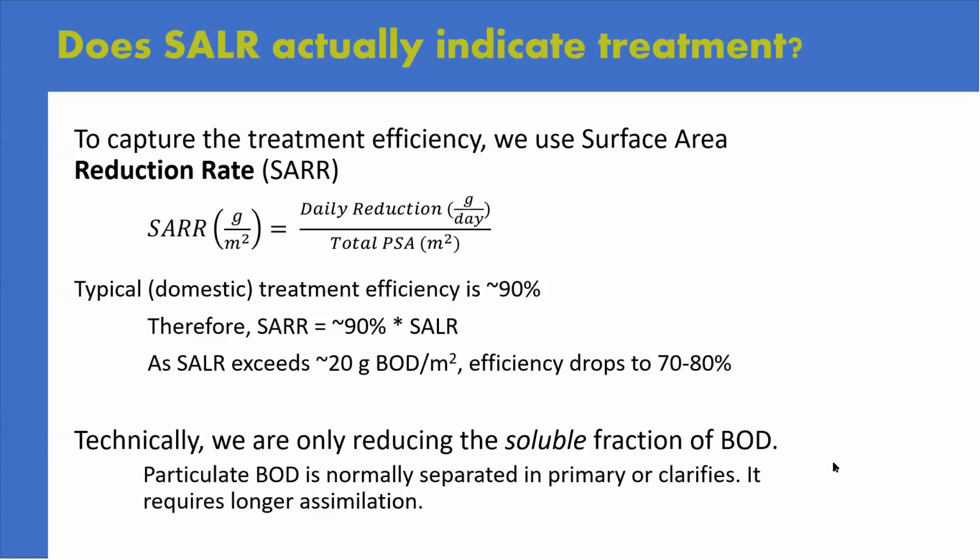So this is just a little blurb about how, when we're actually designing the system, we want to use the reduction rate in our equation, but first we need to determine our loading rate. And the reason why I'm focusing so much on loading rate is because when you do your research online, when you look at technical articles, when you look at research studies, you're primarily going to be seeing things measured as loading rate.